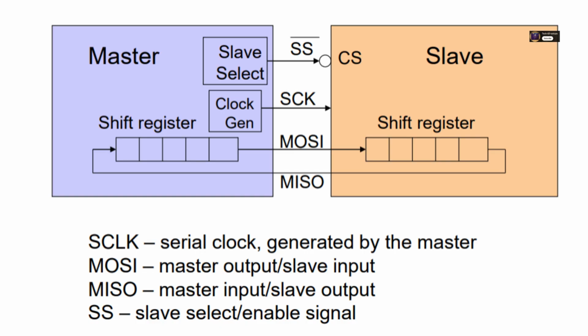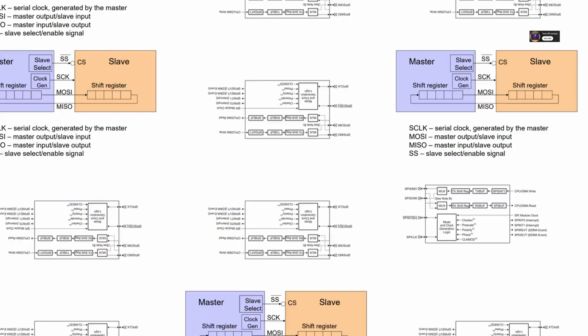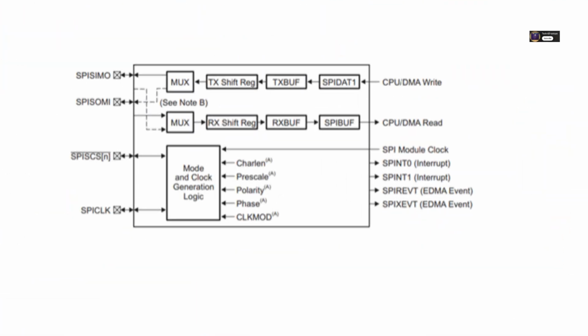And a subtle one, mixing locking and DMA transfers without careful management of the chip select line. If you start a DMA transfer but your code accidentally toggles CS high before the DMA is finished, you'll terminate the transfer prematurely. CS needs to stay low for the entire duration of the DMA transaction. These are the kinds of bugs that can take days to track down if you're not aware of them.